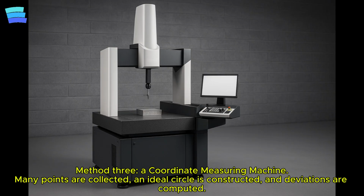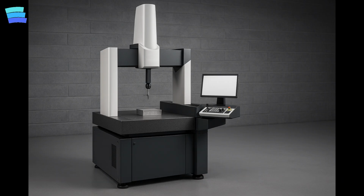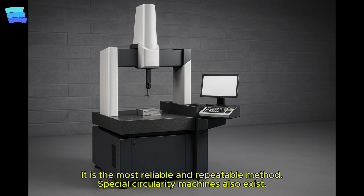3. Coordinate measuring machine (CMM). A large number of points are collected on a section. An ideal circle is mathematically constructed from these points. Deviations are calculated by the software. It is the most reliable and most repeatable method. There are also special machines designed specifically for measuring circularity. We will cover the details of these instruments in later metrology episodes.